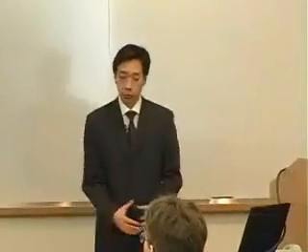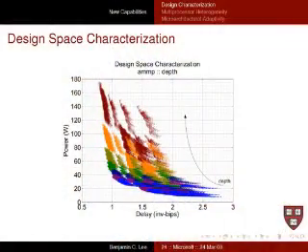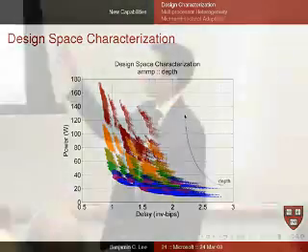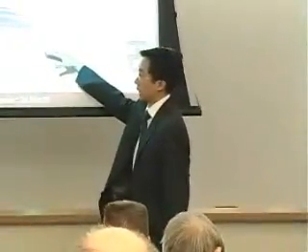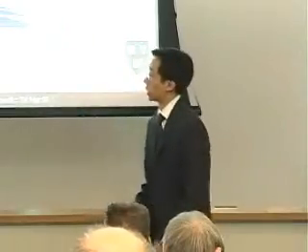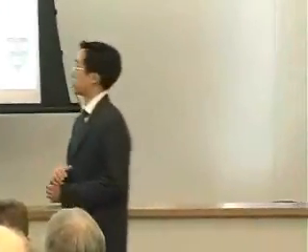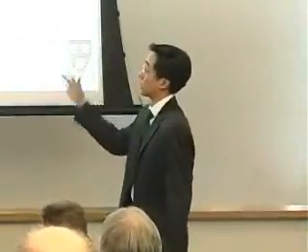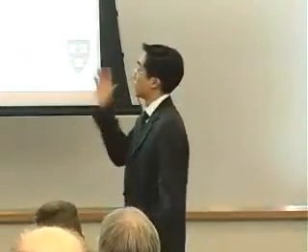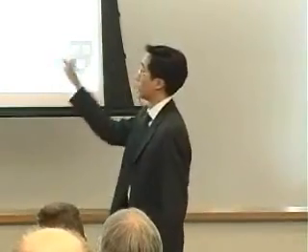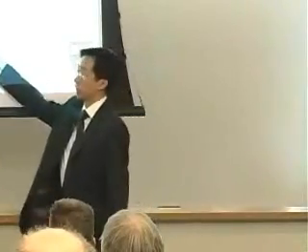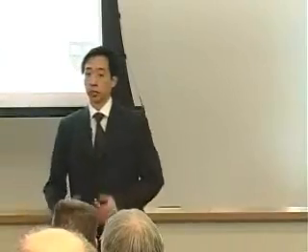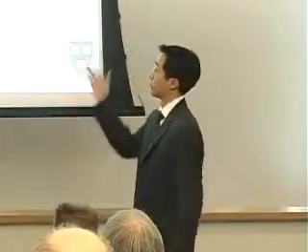We can characterize and visualize the design space in a very comprehensive fashion. So if we take our design space of 375,000 points and plot them all into the power and delay space. Here we observe delay, or inverse performance, on the horizontal axis and power on the vertical axis. And this is essentially the spread that you were asking about earlier. We see for this particular workload, this is spec amp, that the 375,000 points span a wide range of delay values and power values. The color mapping for this figure corresponds to pipeline depth. So the blue points correspond to shallow pipelines, and the red points correspond to deep pipelines. And we consider 10 different pipeline depths, so that there are 10 different colors.